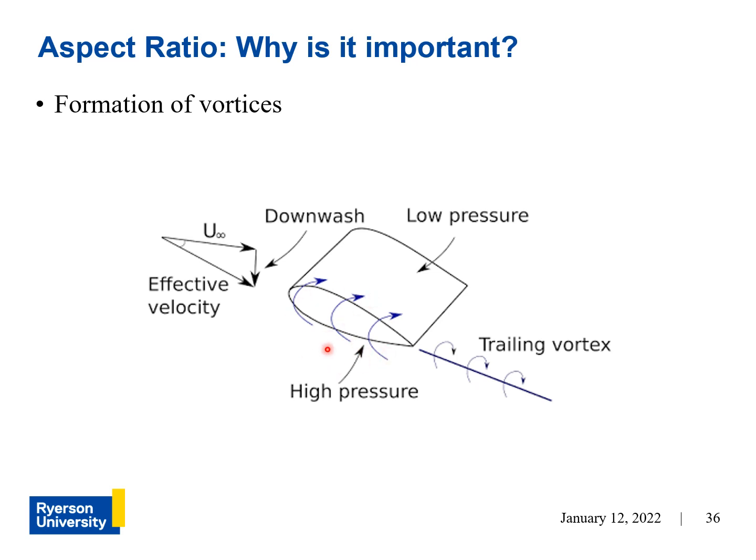And again, in addition to that reduction in pressure difference, the leaking of air causes a circular stirring motion that leads to the formation of these things called trailing vortices right here. Now, this stirring motion actually affects the flow of air around the airfoil, and the oncoming air seen by the airfoil is also affected, and it causes it to be pushed downward here.